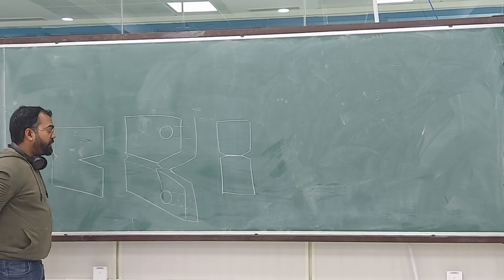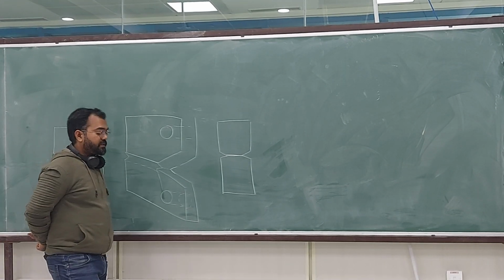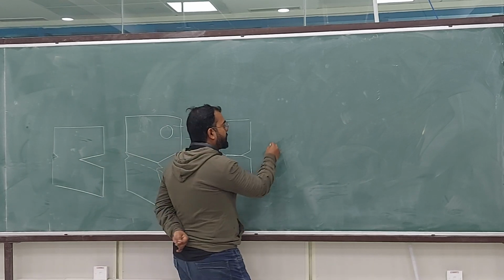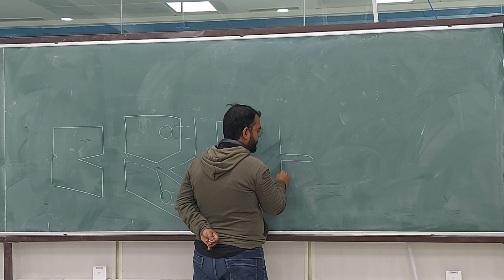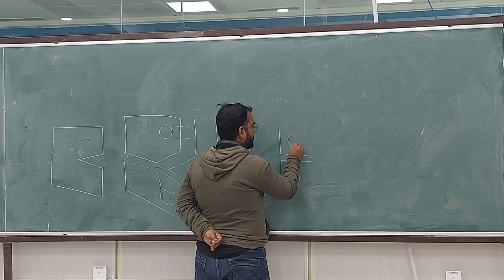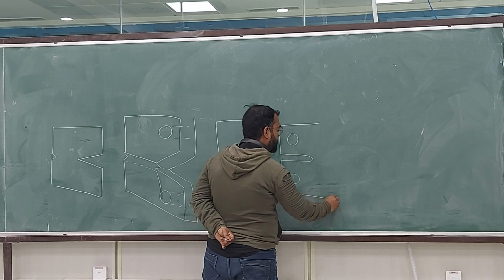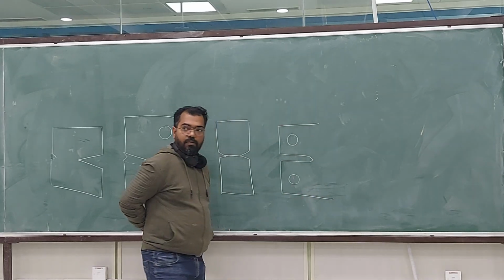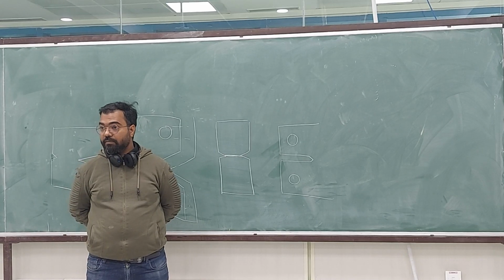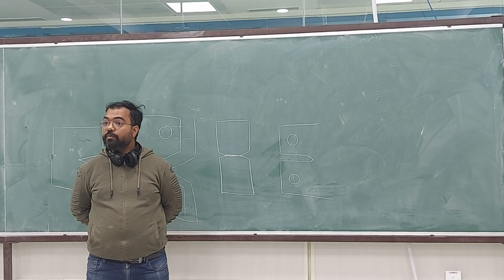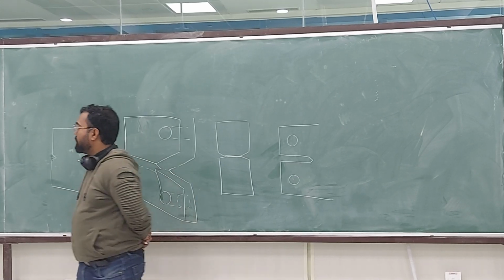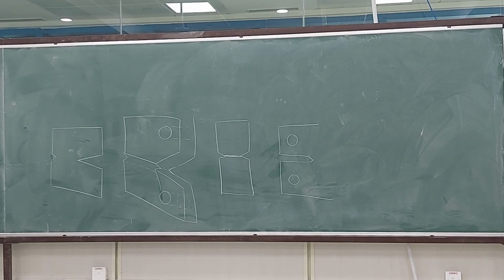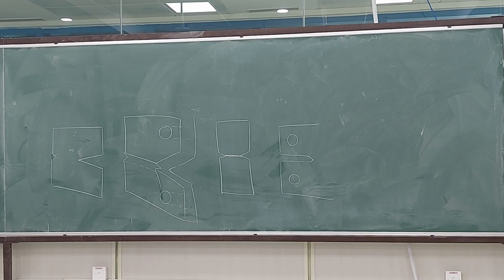So whenever we do any testing related to fracture toughness, one thing you have to make sure is that the crack must be a sharp crack. Okay? It cannot be a notch. It must be a sharp crack. How do we make a sharp crack? What is a sharp crack? Using wire EDM, using wire you could.